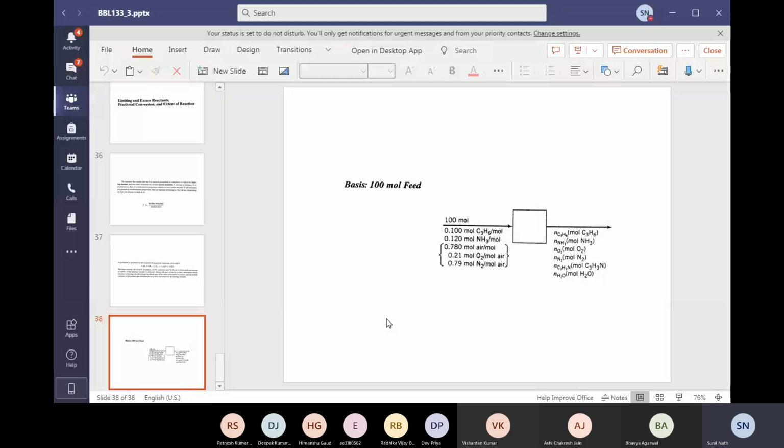Because very often we have to find out what this yield is, and that's a very important number for mass balance with chemical reactions, multiple reactions. There is no one way to do this, but what is the most logical way and what is most commonly used, at least in the commercial chemical processing industry? You always measure how much was fed. That is the fresh feed. If there is a recycle stream, the fresh feed and the recycle stream get combined and form a combined feed.